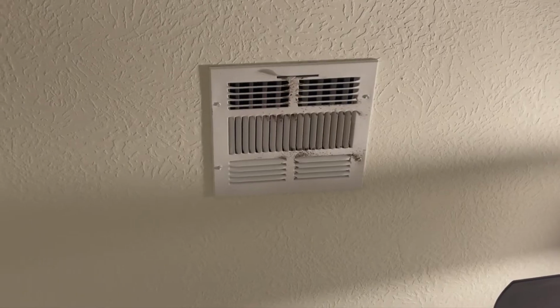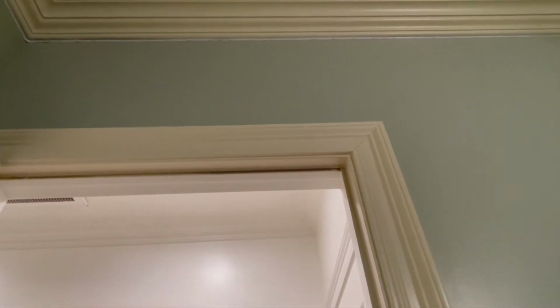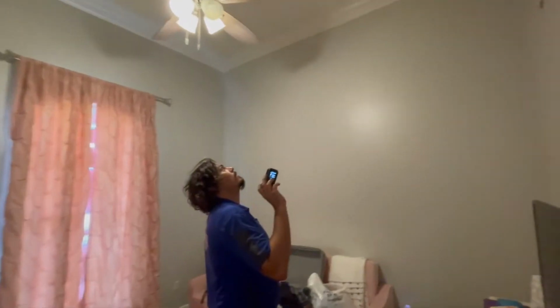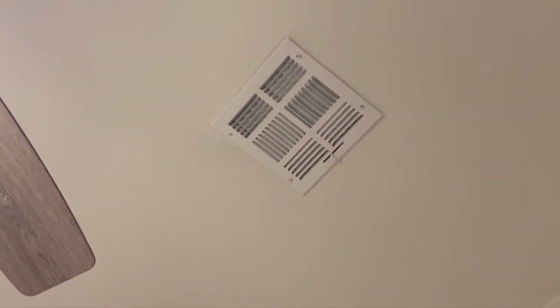Also, if you look at this door right here, you'll see that we have a lot of dust, which leads me to suspect that we have some building pressurization issues, or room pressurization, I should say. This vent is practically closed. We'll have to find out if the homeowner felt that this room was getting too cold or not. No dust on that door frame. Nope.